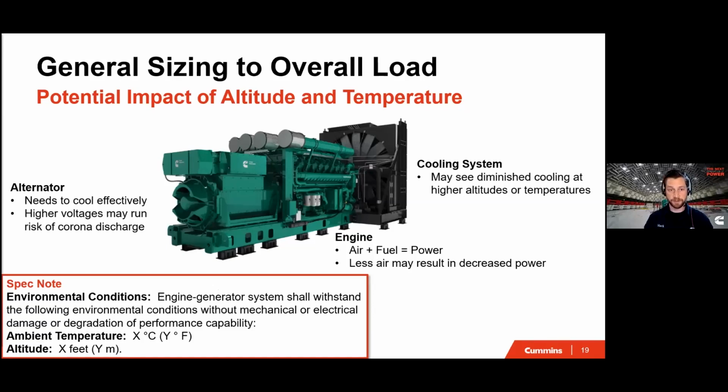So to sum it up for you, keep specifying the known environmental conditions, including the design temperature and the site altitude. Leave it to the manufacturer to provide for you the best fit equipment for the customer's needs. And let the awareness I provided allow you to ask pointed questions if necessary. Keep in mind, emphasis on the word ambient. Ambient temperature shall be measured at the air inlet to the engine generator for enclosed units, or at the room inlet for machines installed in indoor equipment rooms.